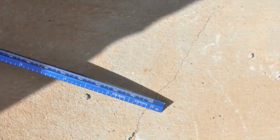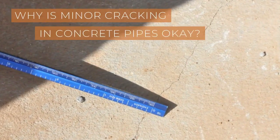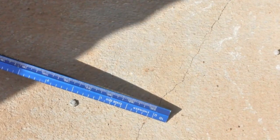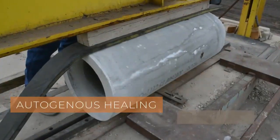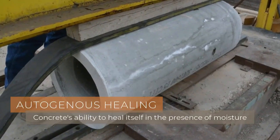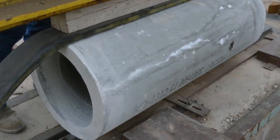One question the American Concrete Pipe Association often hears is, why is minor cracking in concrete pipes okay? The answer is found in the principle of autogenous healing. Autogenous healing is concrete's ability to heal itself in the presence of moisture. The visual indication of autogenous healing is a whitish substance known as calcium carbonate.